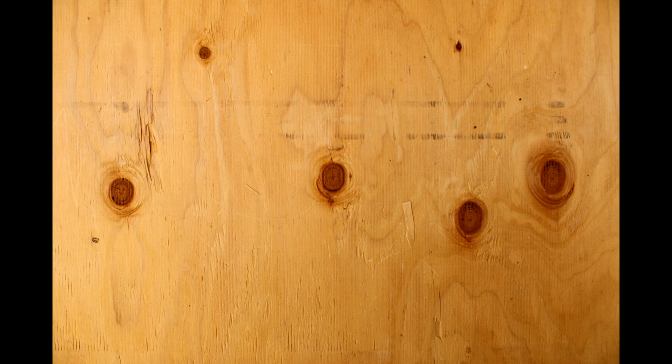When it comes to lumber, as we briefly discussed, you're going to come across certain defects that just come naturally in how the piece is cut. We briefly talked about how plywood has knots or holes cut into it, and depending on the grade of that particular sheet good, they'll either be filled in or left open. Those defects come from the process in which they are cut, and those openings or knot holes are basically from the tree branches that may have been growing from that tree, but once it was cut down, that branch obviously didn't exist. Whereas during the blade cutting, it'll still have that hard knot remaining in the lumber.